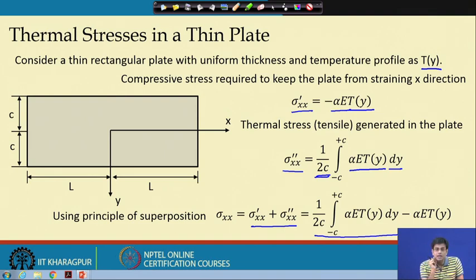Now, you have probably known this from previous discussion, that at the end of the member there is an end effect. So this stress is naturally not valid at the end of the body, because we have the so-called Saint-Venant effect, which is the end effect or the boundary effect of the system.